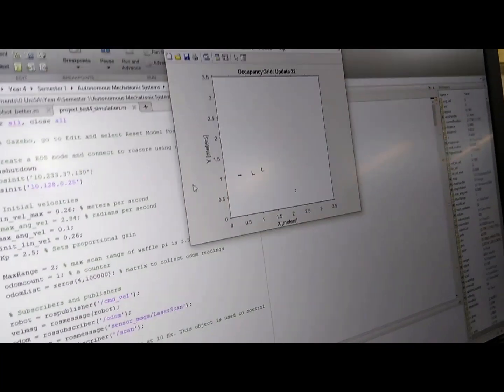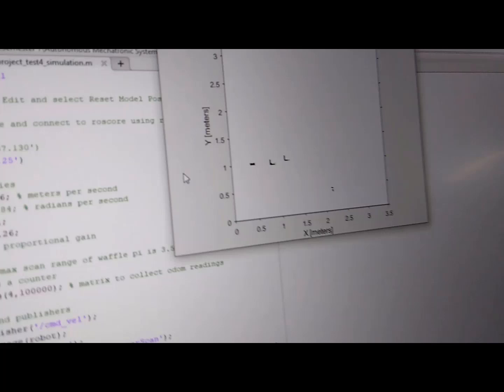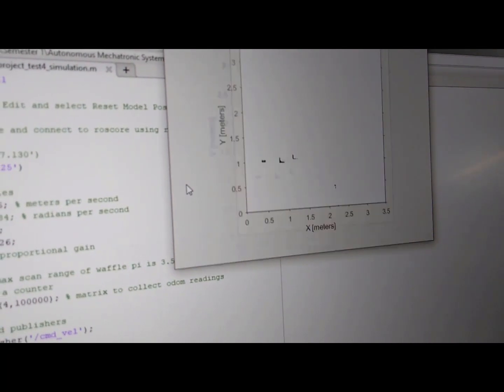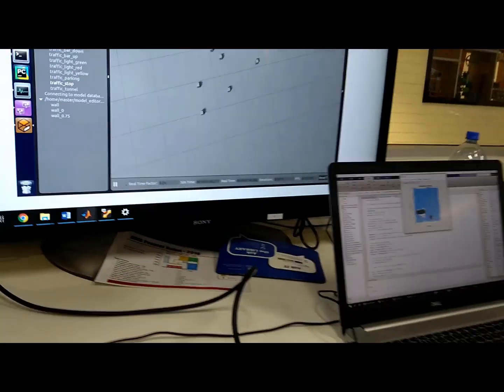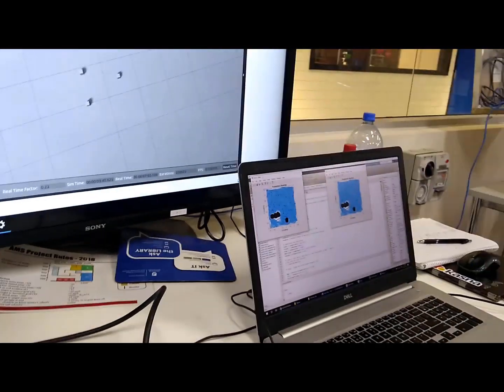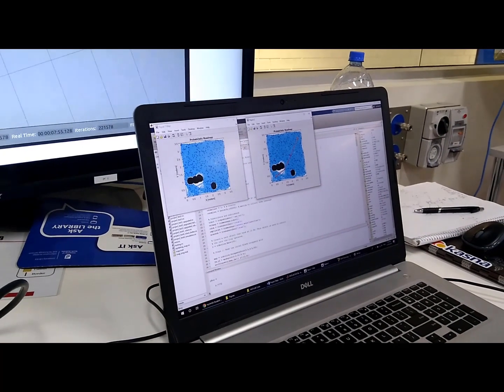It tends to crash and be very annoyed whenever you try to delete or change things halfway through. So what are we actually doing with the LiDAR? The LiDAR is being read into the occupancy grid seen here, which is then inflated, and PRM is used to create a path, which the robot will then follow, as seen currently in the simulation.